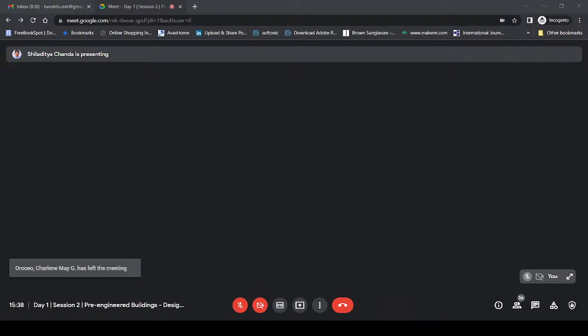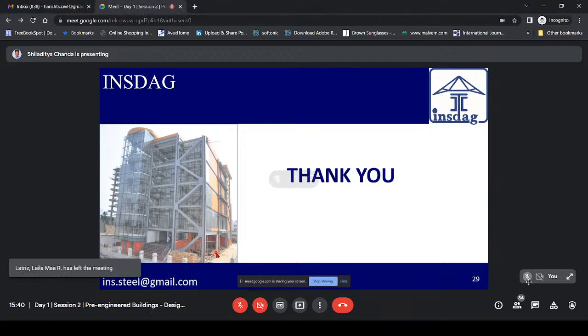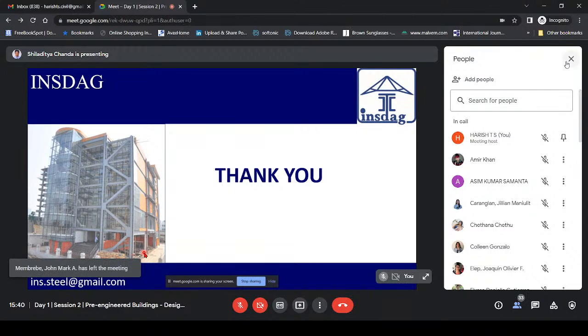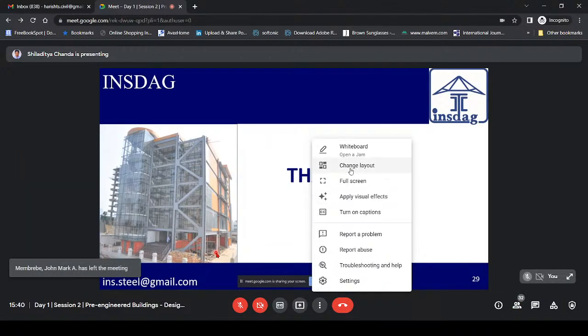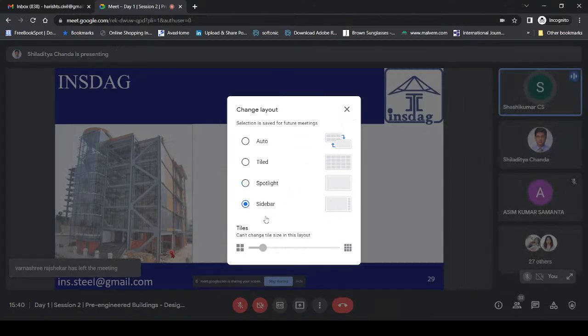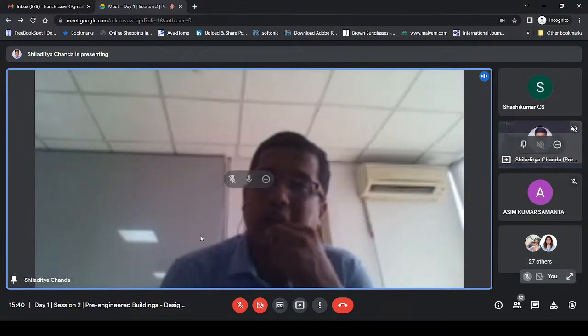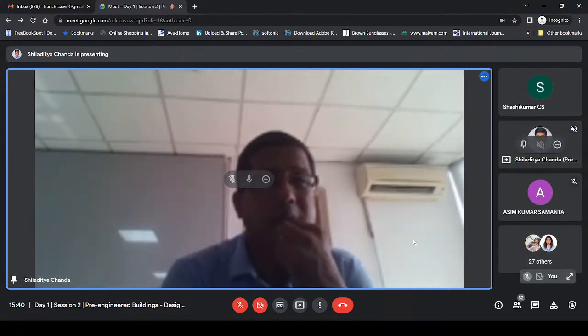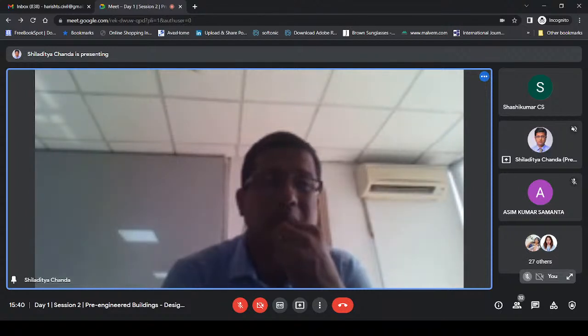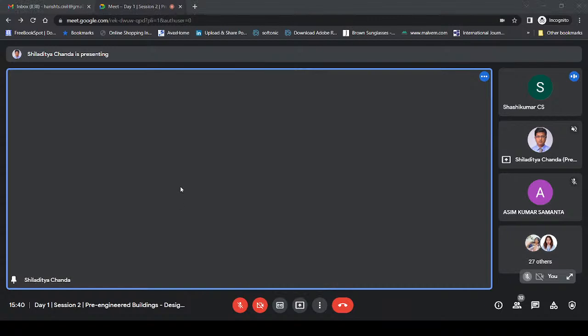Sir, we designed this rafter and this column based on the bending moment diagram. How do we limit the depth of the beam at, let us say, this point of contraflexure, where the bending moment is 0? What is the minimum depth we should provide at that point? Normally, as far as my knowledge goes, or whatever structures I have designed, I restrict to around 250. I don't go below 250 or 275. 275 is the overall depth, and around 250 is the web depth.